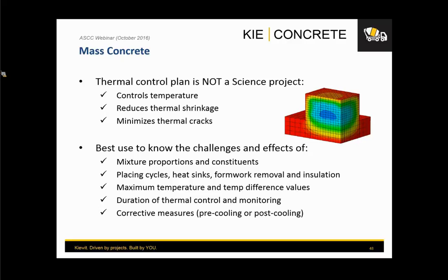And the thermal insulation is different to your curing, okay? Then the maximum temperatures and temperature differentials you're going to achieve. The duration of thermal control, that's extremely important. How long do you need to keep thermal control and how do you need to monitor it? And then obviously the ways that you're going to use to either pre-cool or post-cool your concrete, right? You need to know that.